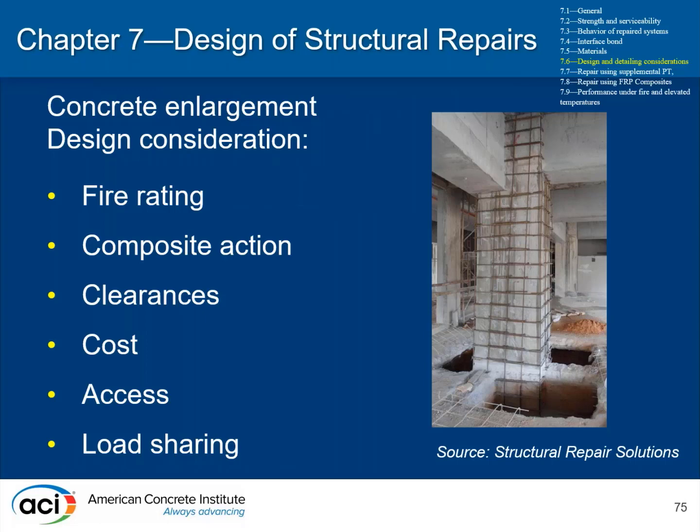When we're talking about concrete enlargement, maintaining fire rating requirements with cover over the reinforcing steel, we'll talk a little bit more about the requirements in the code with regards to fire. But also the other important parameters here are, again, that composite action that's established through the bond that we talked about. Clearances can oftentimes be a parameter that needs to be evaluated, making sure that the minimum heights to maintain clearances with respect to the code or functionality of the structure with respect to the owner's needs.